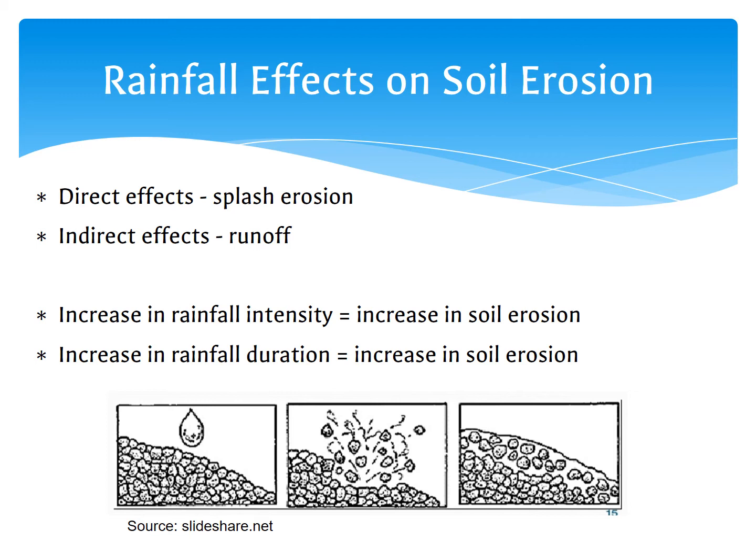In a study in the same article, it showed there was less detachment in clay and clay loam soils, such as the soils present in our catchment. This indicates that these soils are more stable than the sandy soils, since rain splash is a measure of the stability or resistance of the soil to raindrop impact forces.